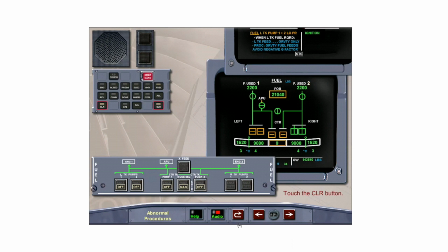The associated engine is now fed by gravity only. Clear fuel by pressing the Clear button on the ECAM control panel.